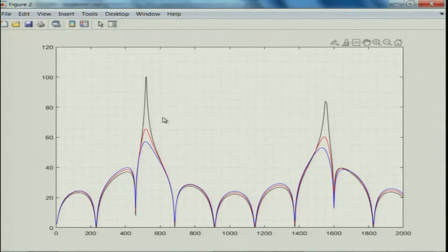With the understanding that if it were 30%, 40% porosity, although you are not able to calculate this due to instabilities and numerical round off errors, the curve would be very similar to these curves, because a highly porous section is nearly equivalent; the results would converge as the porosity tends to 100%, because it is like an open ended section, there is virtually nothing there.